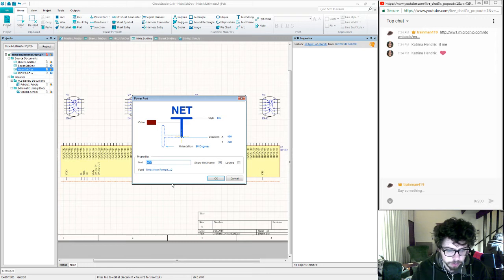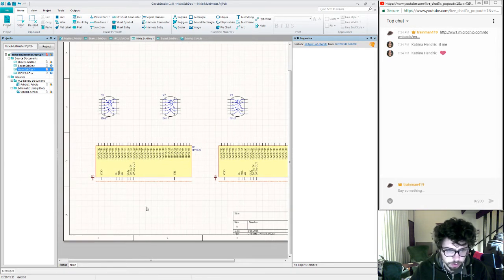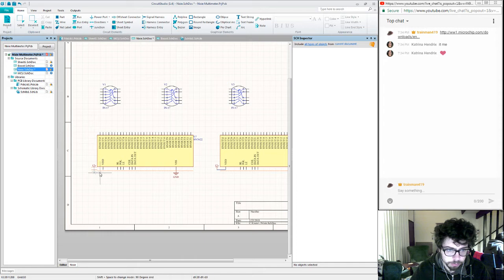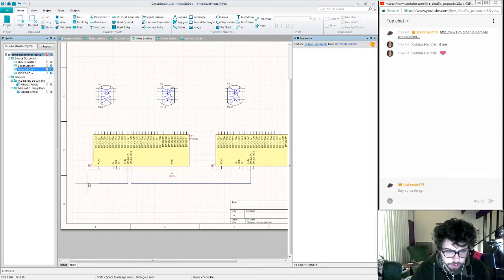So I can start with supply. 12 volts. These are kind of interesting because they're a 12 volt part. I'll also put my ground. And then I'll be level shifting from 3 volts up to 12 with a small, probably a single transistor level converter. I'm going to take the data out from here, run it to the next one, and then I'll run the data in to this side of the schematic.